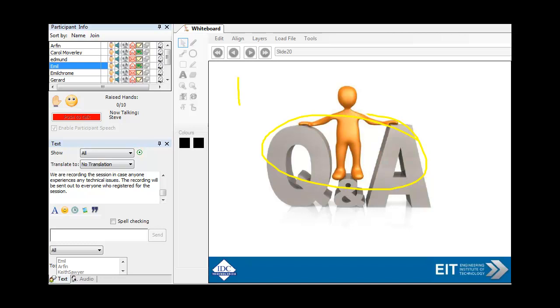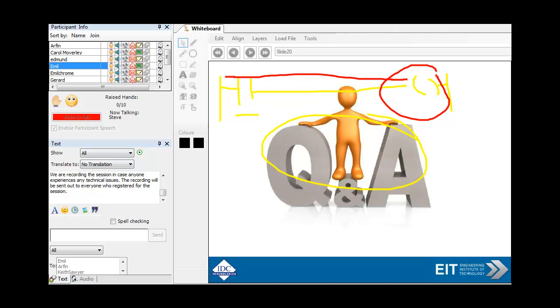If you look at this little ladder diagram here, this is the simplest possible ladder diagram that you can ever get. Let me just change my color to red. So basically this one here is an input, and when it goes on in the field, you push a switch on, there's power flow from there through, and it then energizes this thing here called a coil, and that drives that output on, switch pump on.